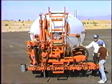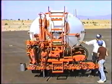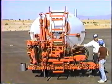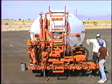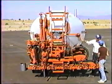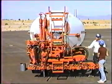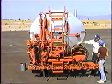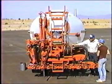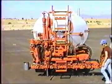We only do that if the truck has front and rear suction valves on the tank so that you could remotely change it. That is, if you were going up a hill spreading, of course you'd have the rear valve open. If you went over the top of the hill going down and you were low in the tank, you might want to open up the front valve. And you could remotely do that if it had the front rear remote controls. A little short tank like this has no need for front suction, so it just has the rear power operated valve. We're coming out of that valve into the main 4-inch line that goes into the intake strainer there. Let's go back around that side.